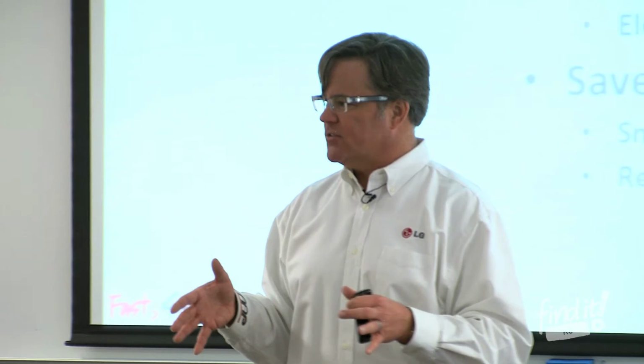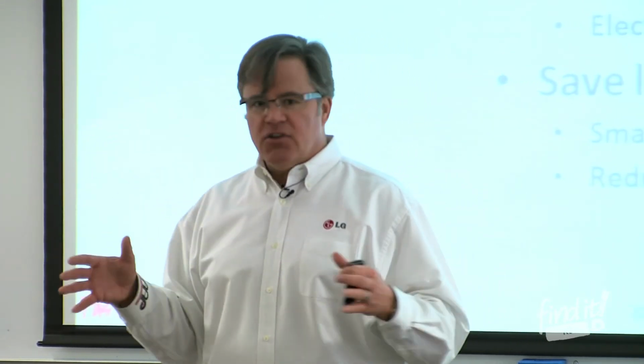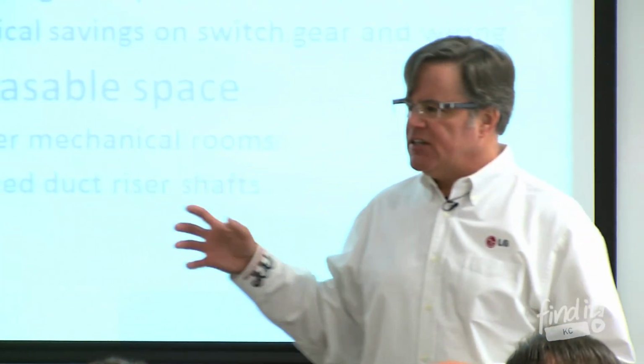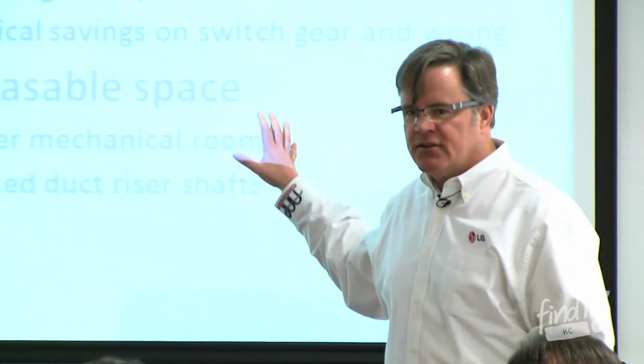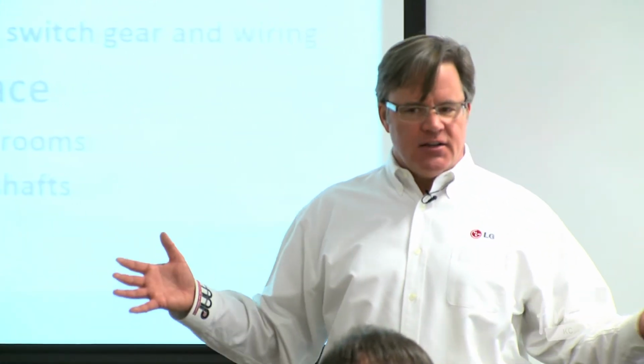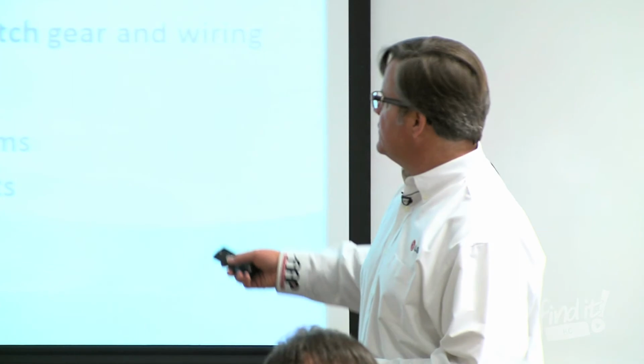We don't have a complicated water system with VFD pumps that have to be maintained by a truly technical professional, because they have to know how all these pieces interoperate together. A VRF system, all that engineering's happening inside that glorified heat pump outside. You just got to keep the coils clean, make sure your electrical connections are tight. That's the maintenance on this stuff.